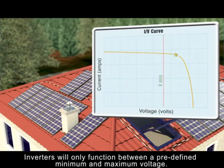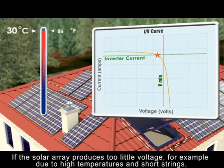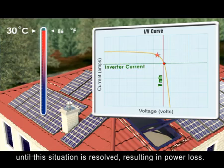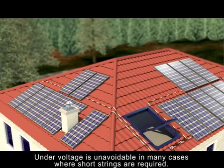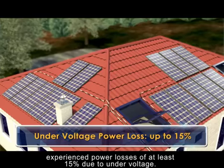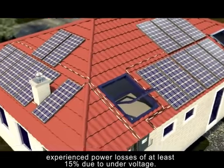On average, partial shading losses amount to between 5 and 25%. Inverters will only function between a predefined minimum and maximum voltage. If the solar array produces too little voltage, for example, due to high temperatures and short strings, the inverter will reduce the string current below the optimal operating point until this situation is resolved, resulting in power loss. Undervoltage is unavoidable in many cases where short strings are required. A survey estimated that over a quarter of PV installations in California experienced power losses of at least 15% due to undervoltage.